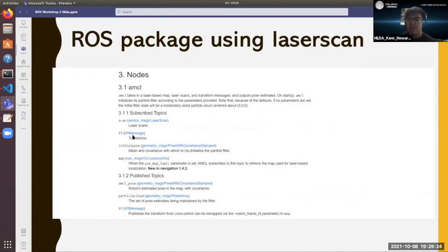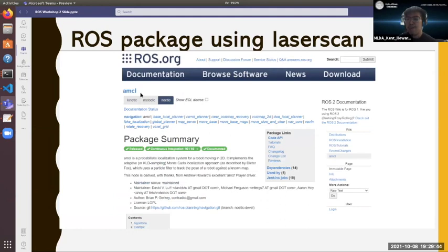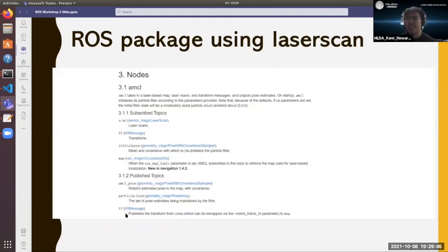It takes in the transform, which is the distance between the center of your robot and the LiDAR. Then it takes in your initial pose relative to the world. This can be GPS data, it can be anything, really. And it takes in the map, an occupancy grid. By simply providing this program with all four, you get the position. So instead of rebuilding your whole program, everything by yourself, ROS essentially allows the community to skip all that and use others' existing programs.